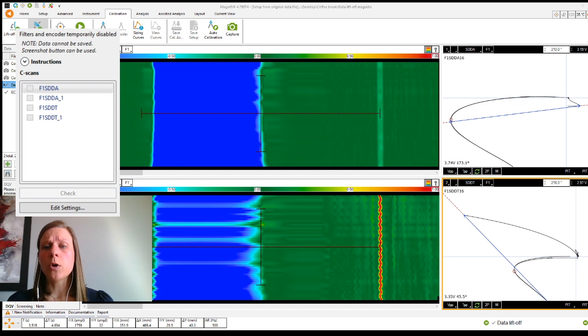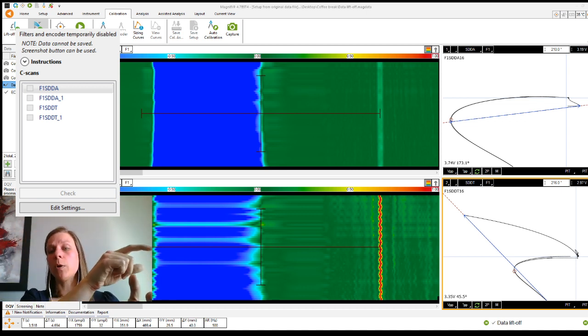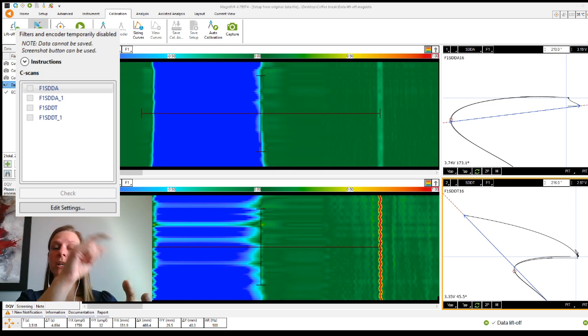You balance the probe, you scan your reference. So if you are working with a spine probe, for example, you will balance the probe in the air, start an acquisition, move the small aluminum reference across the array and stop the acquisition. If you are using a reference plate, you will balance on your plate, start the acquisition, scan in the transverse direction, then rotate 90 degrees, scan for the actual signal, and then stop your acquisition.